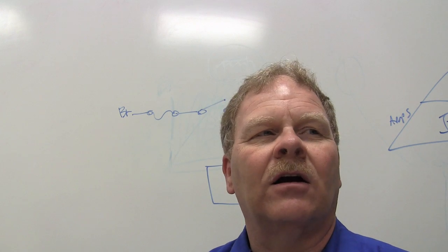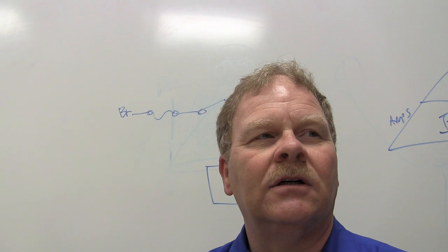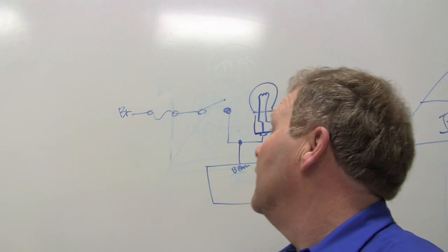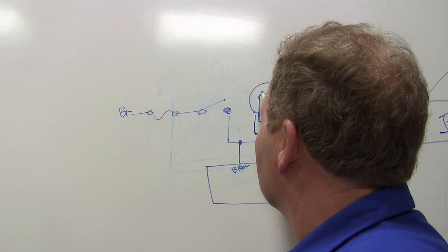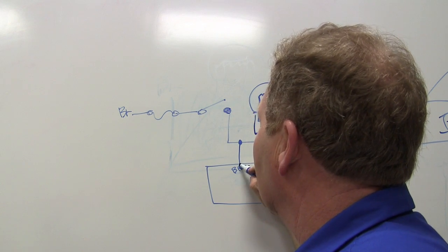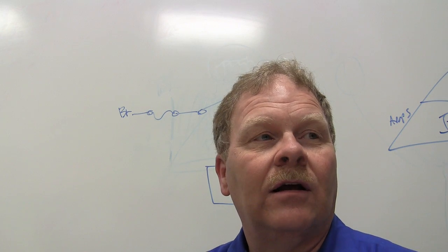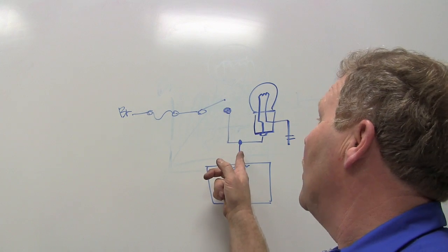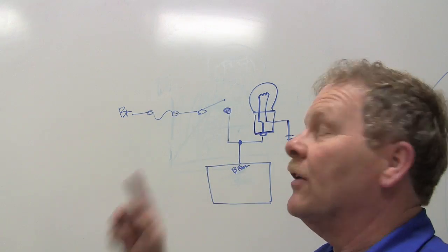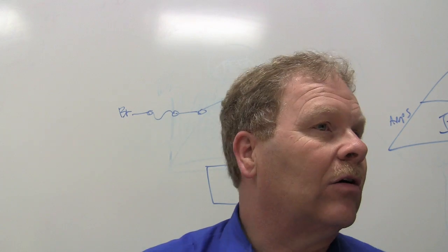It doesn't care a rip about voltage. It ain't looking at voltage, not on that. It's looking to see if that switch is closed. It's looking to see if that ground is coming through that filament into there, if you've got a cruise control. So you're saying that switch don't make any difference? That switch makes a difference, but what happens to this ground when you close that switch? It just goes away. Yeah. It's no longer a ground.